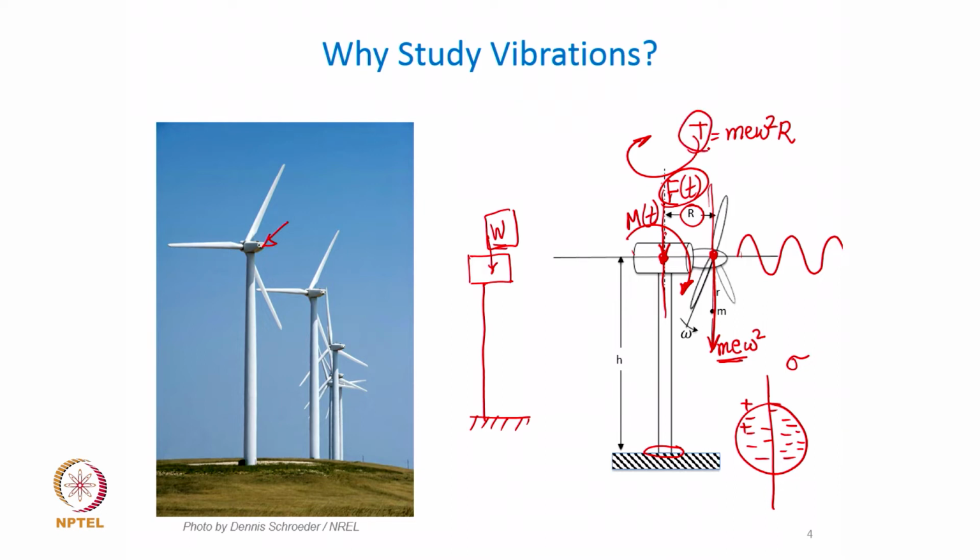What about the twisting moment? This is going to create shear stresses in this cross section, and you all know from machine element design, all these stresses, the stresses due to the axial load, due to the bending load and due to the torsion which is going to be basically the shear stresses, they all will combine to form the net stresses induced in this particular cross section, and you will have to account for all these different kinds of stresses in the cross section to estimate, using an appropriate failure theory, whether this column is going to survive the stresses induced in the structure.